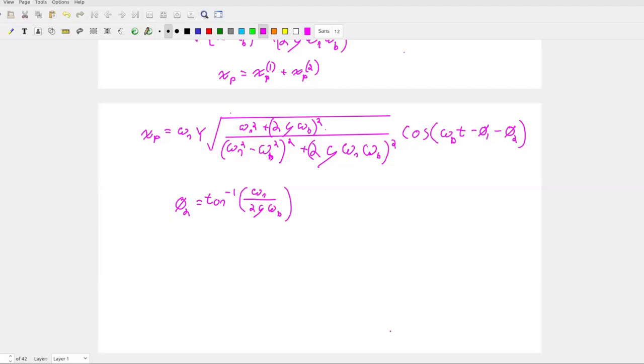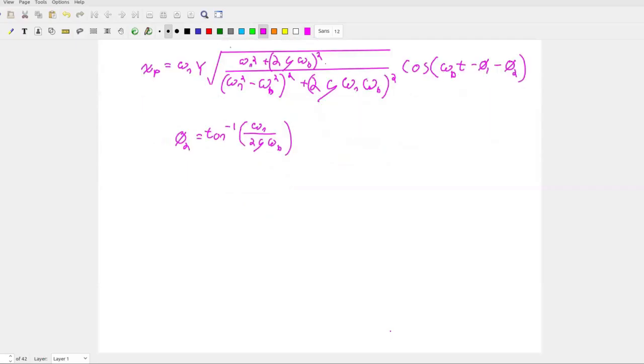Right? That gives you x_p, you have a particular solution. You could figure out where your mass is for any point in time t, but that's not really what we're interested in design. We're interested in the transmissibility and how forces move through it. Again, we can always talk about this in terms of damping and stiffness, but it's really a game that we're playing between the ratio of our driving frequency and the natural frequency of the system, right?